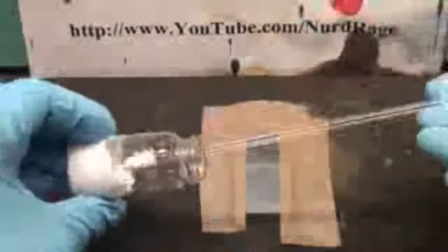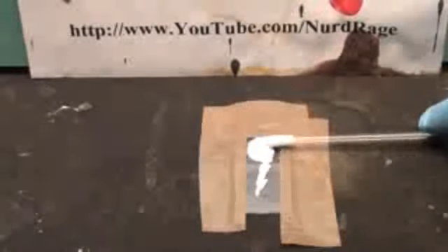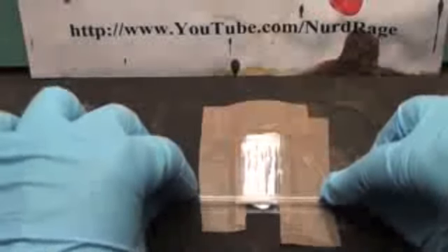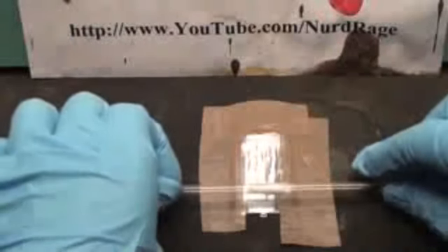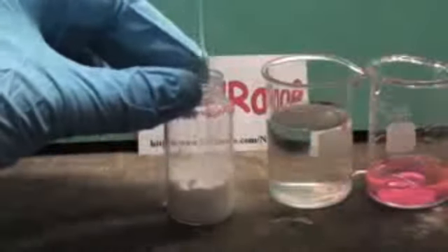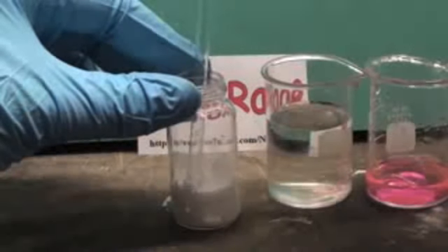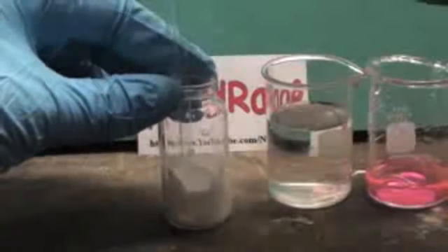Now tape it down on three sides about half a centimeter from the edge. We're using the thickness of the tape to control the thickness of the titanium dioxide layer we'll be applying. Now take the titanium dioxide paste, dab it on, and drag a glass rod over it to smear it out. It looks like my titanium dioxide doesn't have enough water in it and is leaving these streaks. If this happens to you, add another few drops of water to the titanium dioxide and try again. Don't add too much water though, or it will be too thin and won't form a solid layer. Here we go, this is much better.